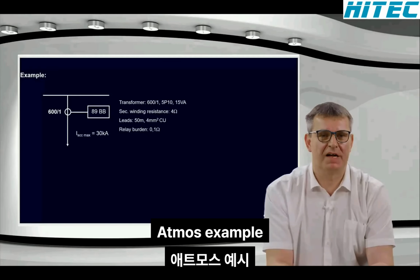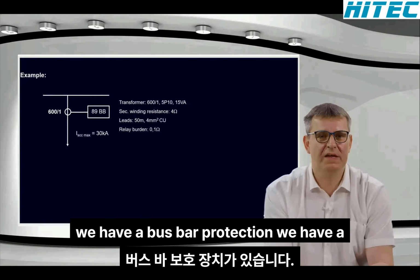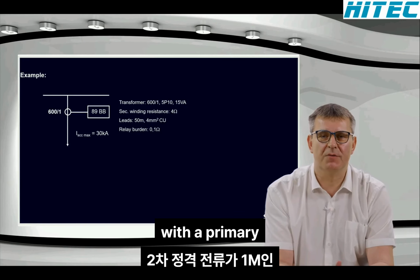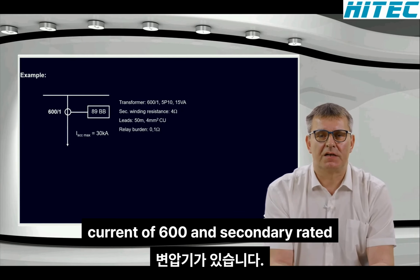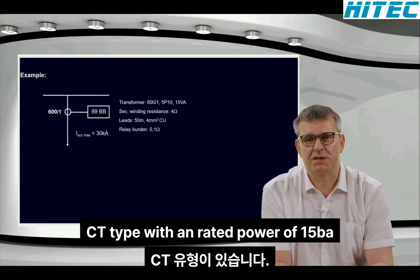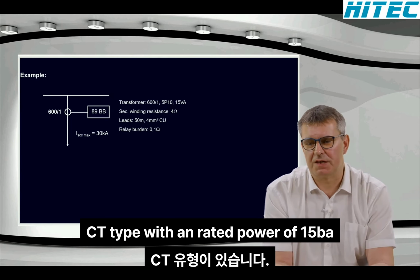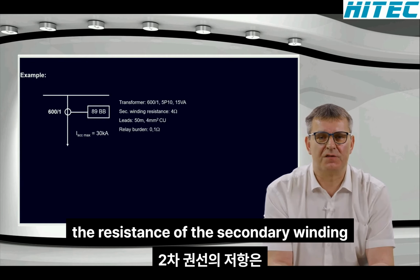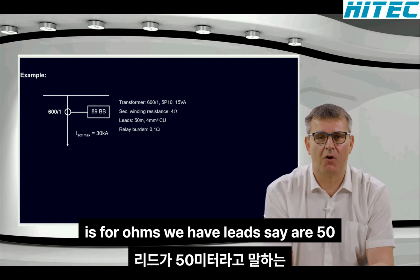A small example. We have a busbar protection. We have a transformer with a primary current of 600 amps and the secondary rated current is 1 amp. We have a 5P10 CT type with a rated power of 15 VA. The resistance of the secondary winding is 4 ohms.